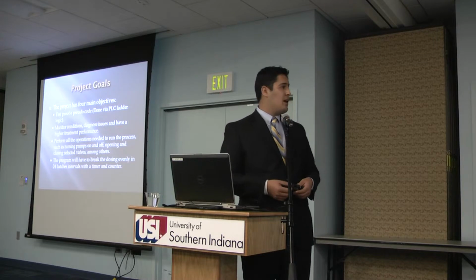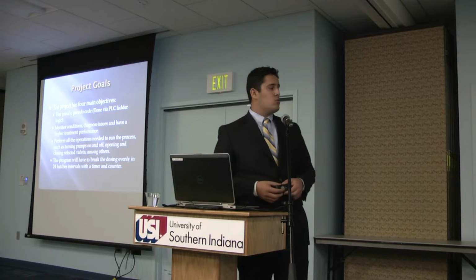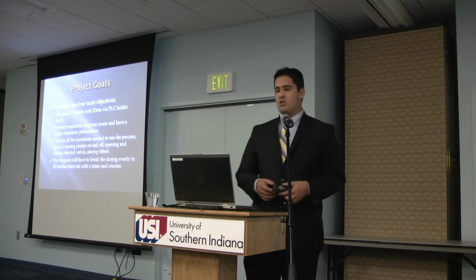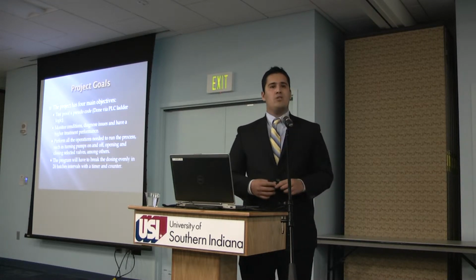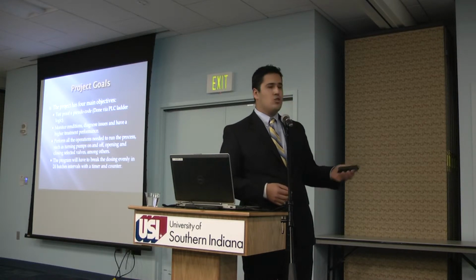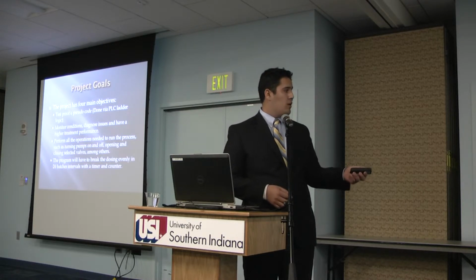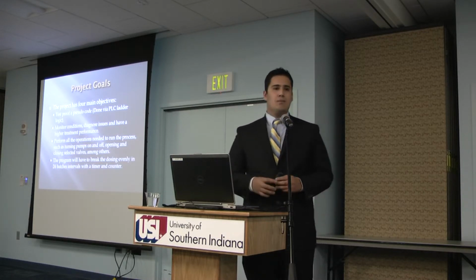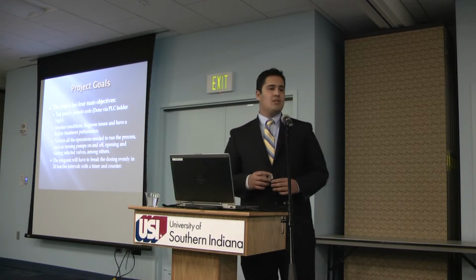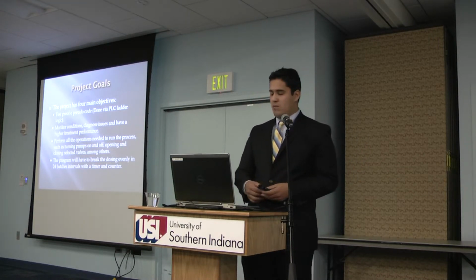And this will also have a timer and a counter to specify to the program when to stop. Cycles will be done as a 24-hour batch, as a 24 doses batch. Once the counter reaches 24, it resets the whole program and it starts over again. But also, if the counter has not reached 24 yet, the timer will be important because it will establish a 60-minute interval, which will avoid overdosing in the system. Once it reaches 60 minutes, it will count as one batch in order to keep the system stable.